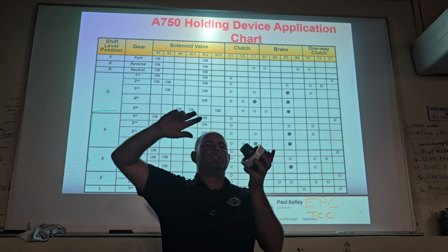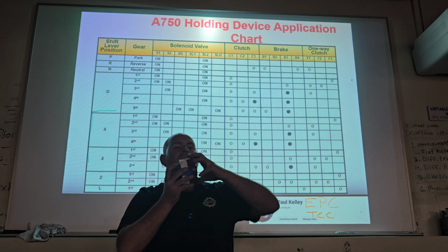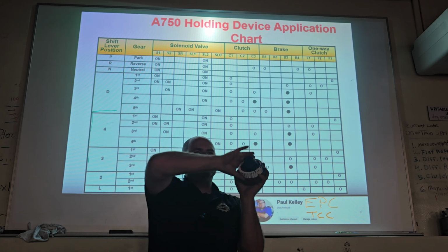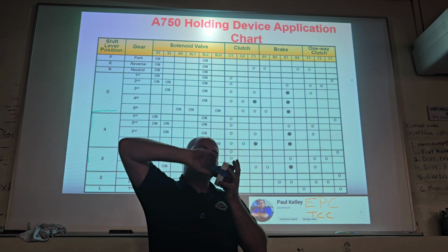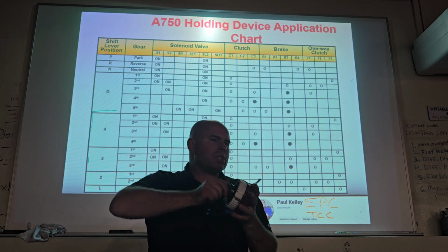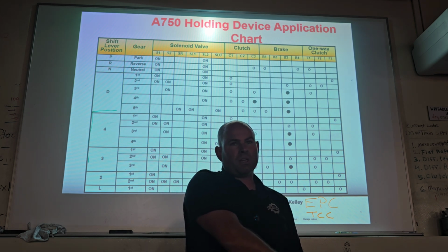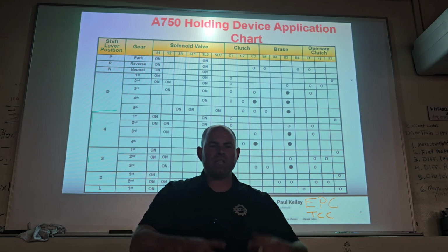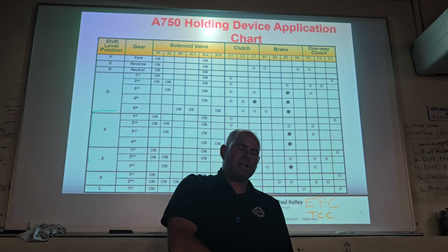So remember, clutches apply and turn, or clutches apply and hold. Make sense? So like if you have a slipping clutch or a brake, right? A brake would be the same as a clutch, except it just holds it. So if I want to hold this carrier, that would be the job of a brake. But if I want to turn the sun as an input, that would be the job of a clutch. If the clutches are slipping, you're going to have a transmission slip. On an electronically controlled one, remember what I showed you, you're going to get a DTC. So if you got a code set for slipping clutch or whatever, you pretty much know you got a mechanical thing going on. Now that may be a hydraulic leak, or that may be literal burned clutch plates, but that's not a shift solenoid.